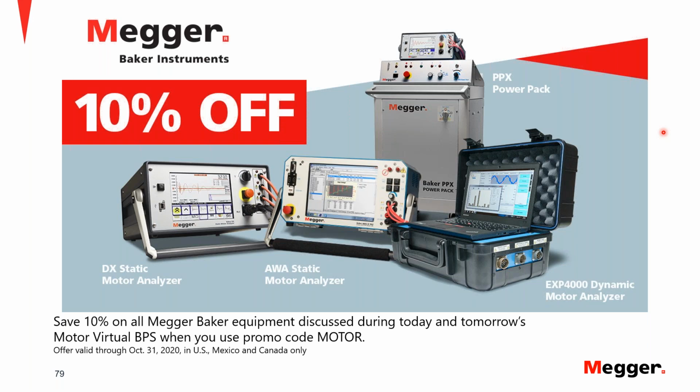And depending on how big that frame is, that will tell you how big the capacitor that the motor insulation forms is. So in order for me to tell you what machine you need for a particular application, the voltage is not enough.